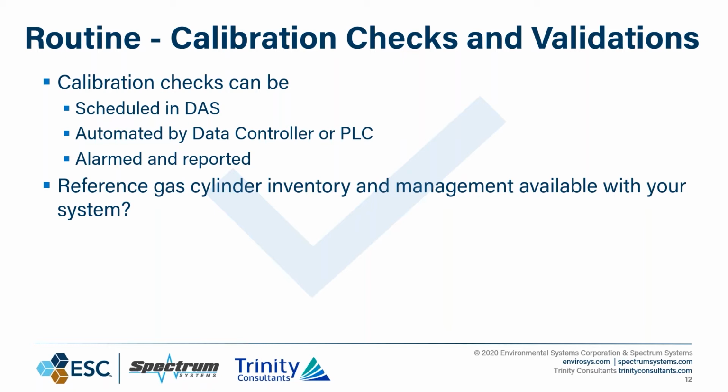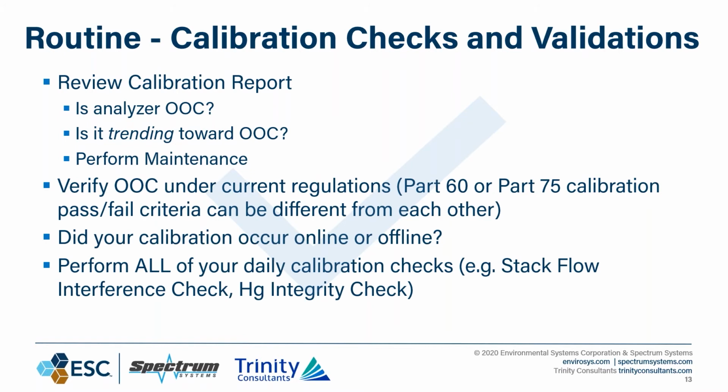And the last part of this routine is, if you're going into a weekend, you need to understand what your gas pressure is and what the minimum requirement is for your facility to do these cals. Because the last thing you want is to go into a weekend on the margin. Let's say your requirement is 150 pounds of pressure in the cylinder, and you went into the weekend at 165. You could theoretically drop below, especially on a Memorial Day weekend with low staff, with a cylinder that might be out of compliance doing these calibrations, and that can cause some trouble. So make sure you check the pressures, swap out where possible, and give yourself some headroom, especially on weekends or holidays.